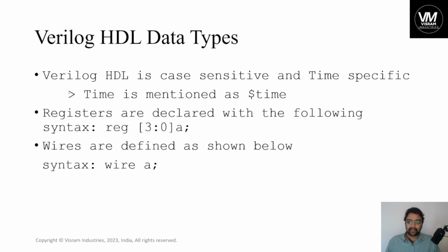And then, Verilog HDL is case sensitive and time specific. You need to mention time in this way when you are mentioning the clock. For example, in the previous lecture we used $time in the EDA Playground to show when the input has been printed, when the output has been printed, and in the counter example.